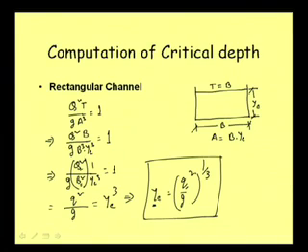But critical depth does not depend on the slope. Critical depth is not a function of slope; rather, we can calculate the critical depth in terms of q and the g value. So critical depth can be calculated directly.